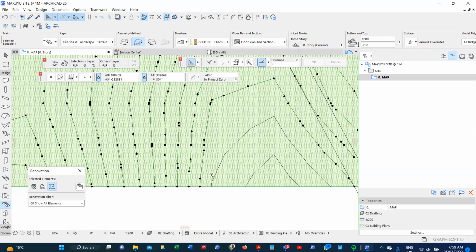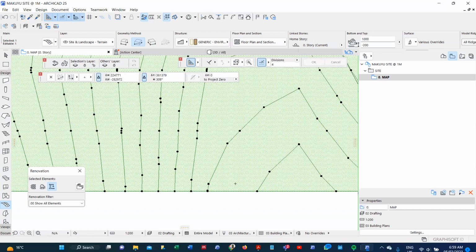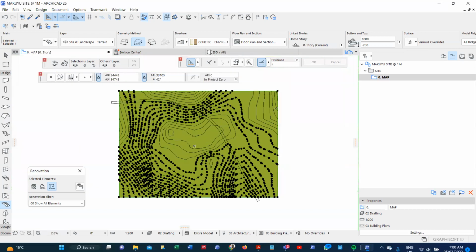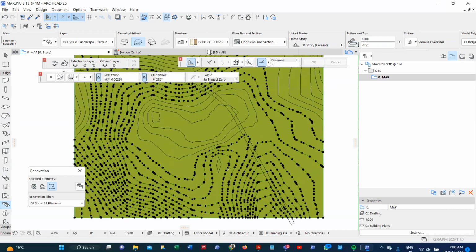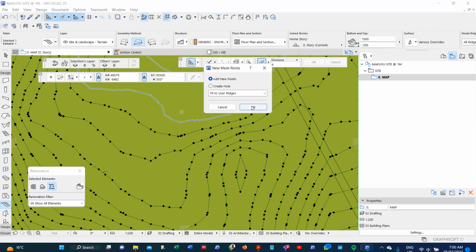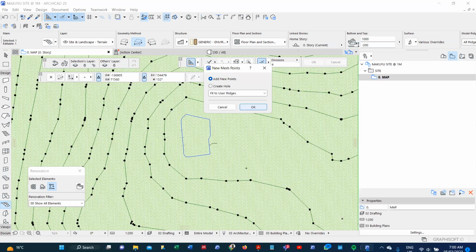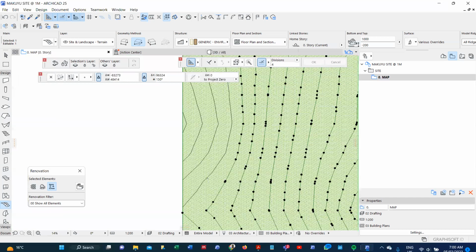So as you can see, for those contours that are running throughout the site, by the time I touch that, I'll have covered most of them. Most of the contours are already placed, apart from the ones on the other peripheries, and the ones that are showing our ridge that are not touching the periphery. So I'll come in and place all those contours. Also come to this side and sort out these ones.